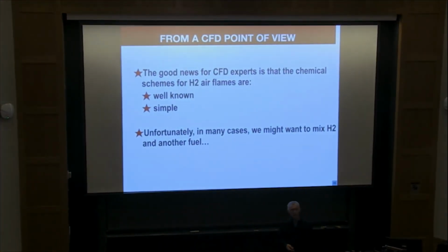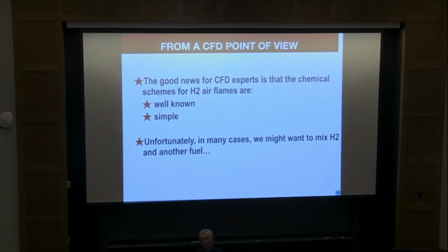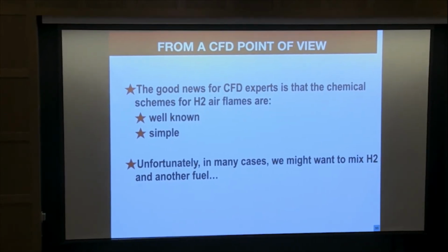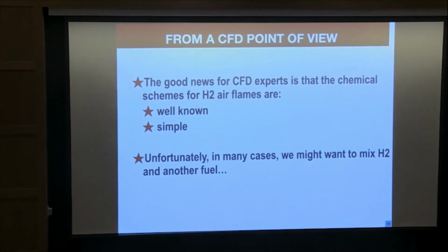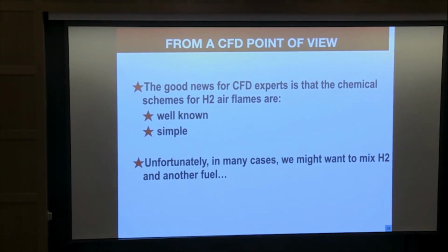Since we talked about CFD, there's one nice thing about CFD, which is that H2 is simple. That's the only fuel for which we have a full scheme at almost no cost. That's the only good news for CFD. There are also no drops, no problem of two-phase flow combustion. So that's good. The problem is that a lot of people will want to mix H2 with other fuels. So that's bad. If you want to mix H2 and kerosene, then we again are in trouble.